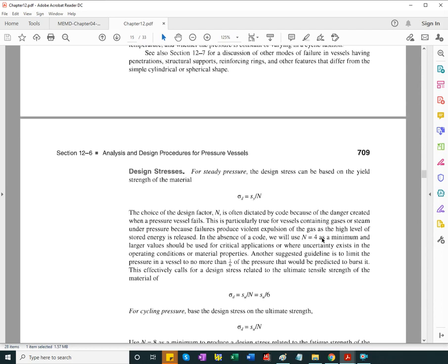What the design procedure is, to repeat myself, make sure you use the right equations. If it's thick wall, the stresses calculated with the thin wall equations will be lower than the actual ones. For thick wall cylinders and spheres, the thick wall equations will give you more stress. The error is bigger, the thicker the wall is.